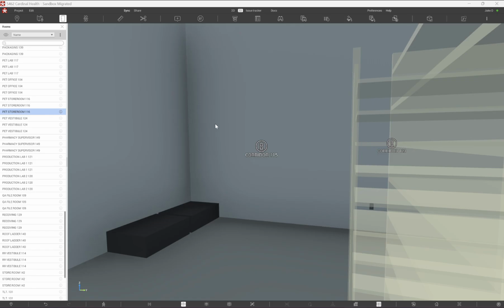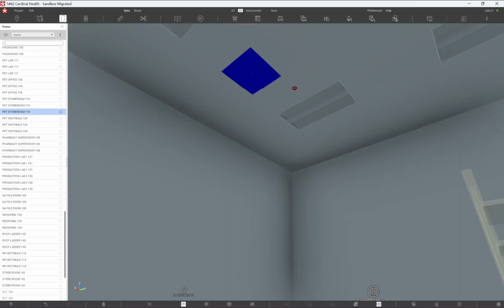And one useful on-site tool that was brought up in some of these Revizto kickoff meetings that I told you about, if you go here, you can generate a QR code for any of the rooms. So the room you're currently in right here, or generate QR codes for all rooms. So you could go on site, print them, and post them on the wall so that when anyone comes in, let's say they need to view what it's going to look like in the finished model, just scan the QR code and it'll bring you directly into the room and you can see exactly what you need to look for.